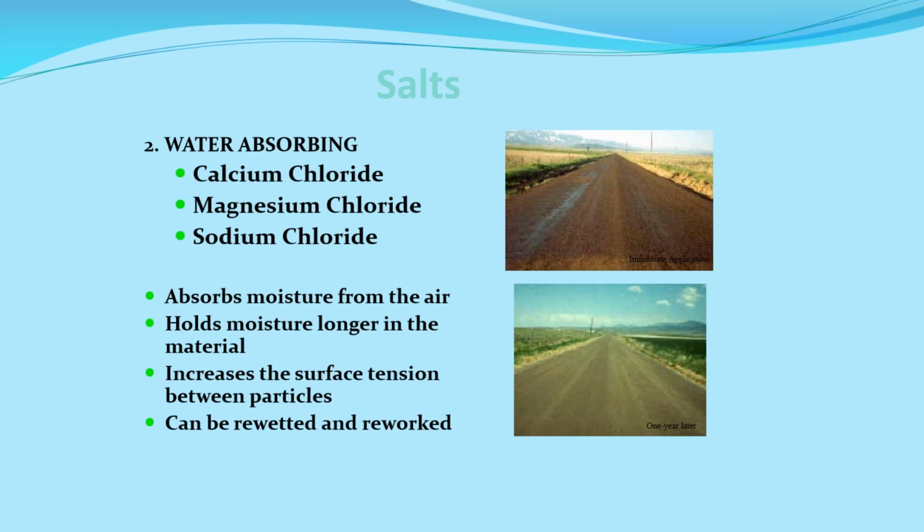Okay, so sodium chloride, I have a few agencies that use sodium chloride to stabilize roadways, but generally speaking, their salt content in the roadway is pretty high. I've got one agency that has a natural well that is a sodium chloride well that has some magnesium in it, and they use it right out of the ground. And it works well, but they have some issues with it.